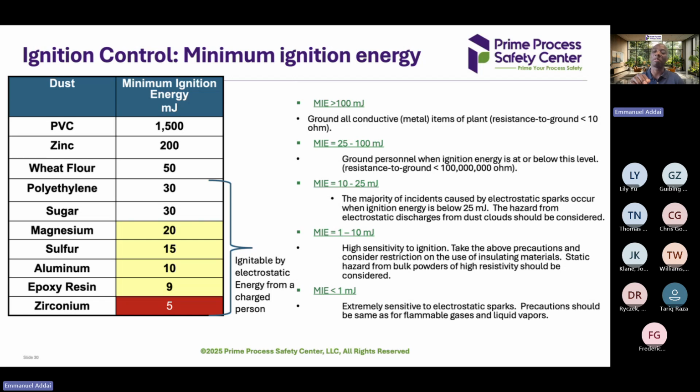Sometimes I have been to several facilities where they have good intentions, but the applications are actually poor. They have static dissipative shoes, but the floor is an insulated floor, or the floor is really dirty. So anytime you use static dissipative shoes, you need to ensure that the floor is also conductive. That is very, very important. And this is something we can help with. We have been to several facilities to do electrostatic hazard assessments, take measurements, and guide the client on how to mitigate any hazard that will arise from electrostatic discharge.